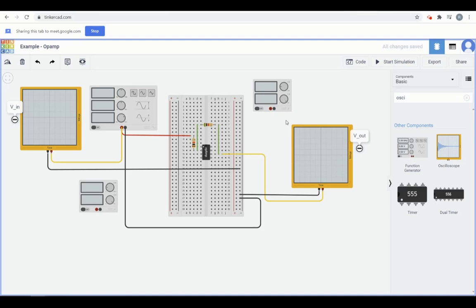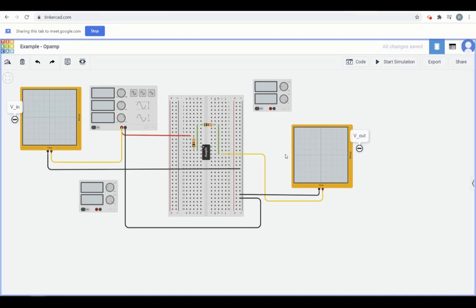Now all I need to do is power this circuit. Everything else is done, right? Is there anything left? Pin number 3, that is input. Yes, this needs to be connected to ground. So I'm going to take a wire from here, make it turn and go here.